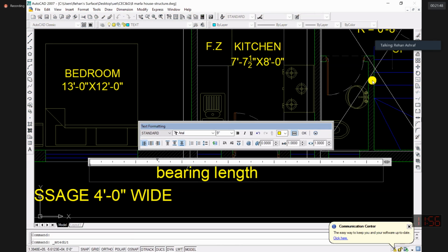And minimum it should be 3 inches or 4.5 inches. 3 inches in the case when there is a concrete connection, like a concrete beam supported over a concrete column, provided that there isn't much load from the beam. If the load is greater, then at least you should provide a bearing of 6 inches, okay? Or preferably whatever is the dimension of the supporting member.